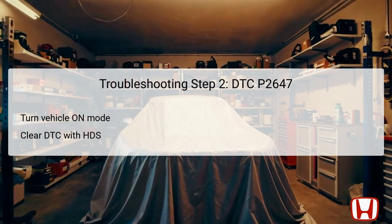Moving on to the second troubleshooting step, the vehicle should be turned to on mode. This allows systems to initialize and prepares for diagnostics. The next action involves using the Honda Diagnostic System, HDS, to clear the DTC from the system.